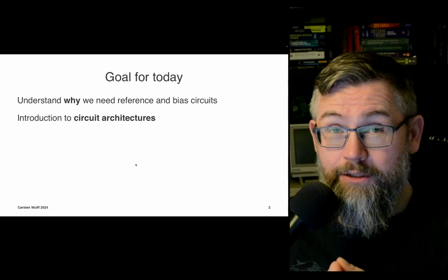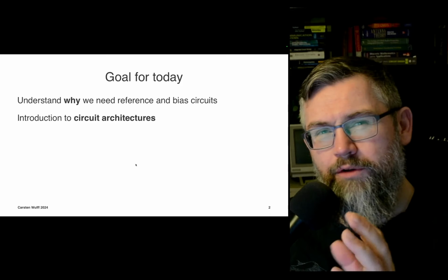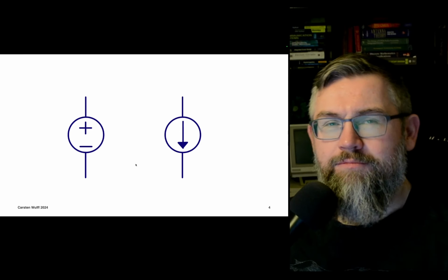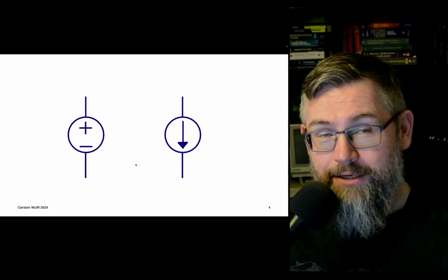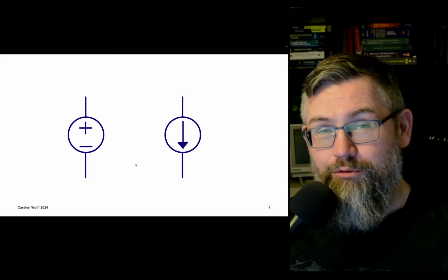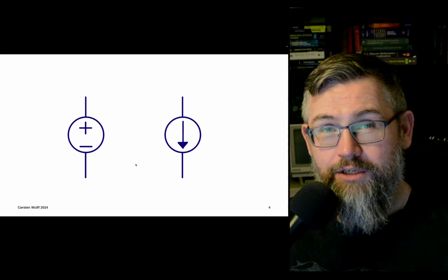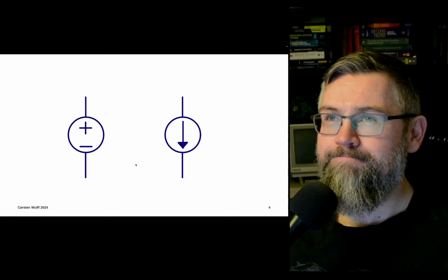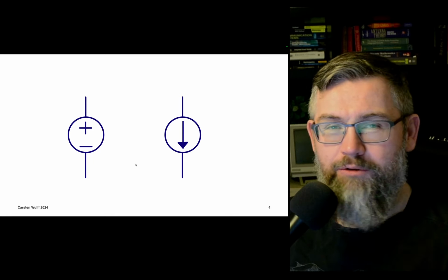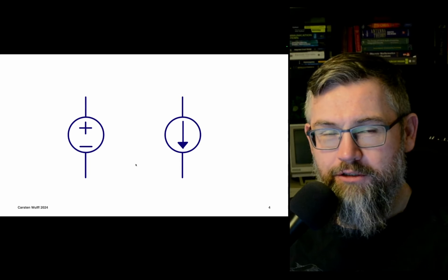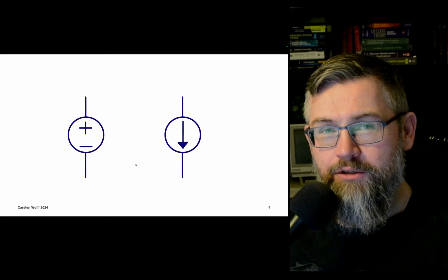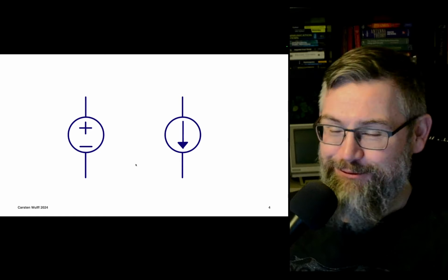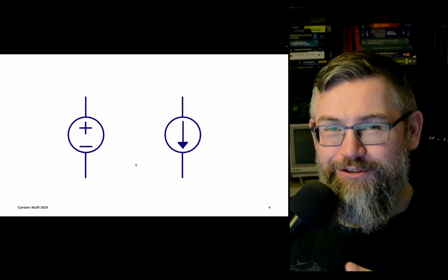for integrated circuits. When you first start out in integrated circuits, in your schematics, in your test bench, in your SPICE simulation, you will use these two symbols, a voltage source and a current source. The voltage source, you can just put in the voltage and it will always force that voltage. It has what we call zero source impedance. It doesn't care what the circuit is. If you say it's going to be 0.5 volt, then it's going to force 0.5 volt.